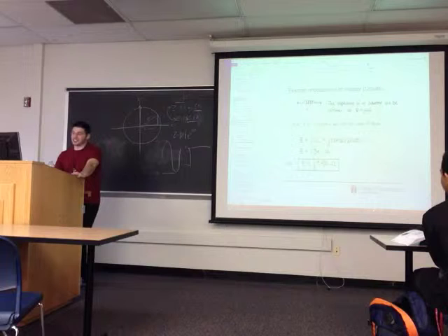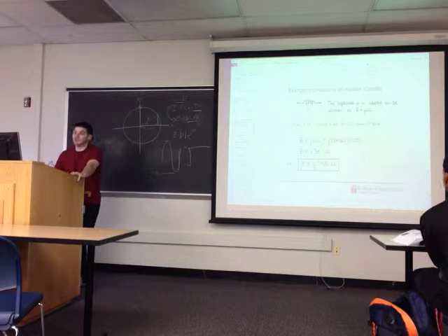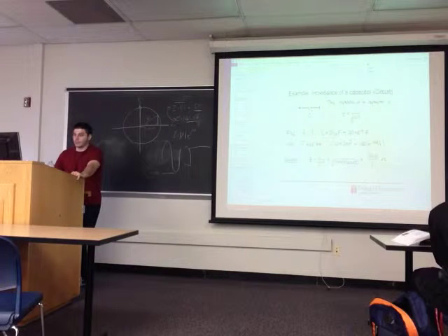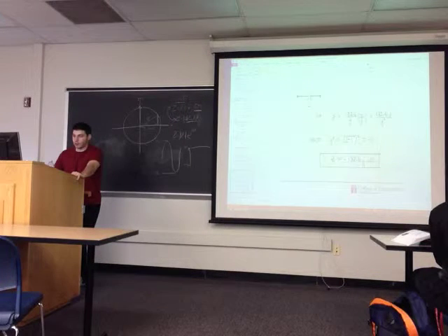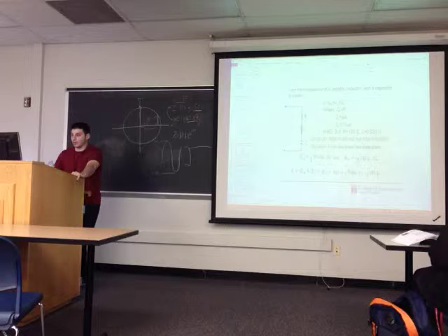So, just to go back, what we're going to do is plug in our values of omega and our values of L. We plug those values in, we then get our impedance of that component, the inductor. And the same goes with the capacitor. And then we add those two parts up, and we're left with this.